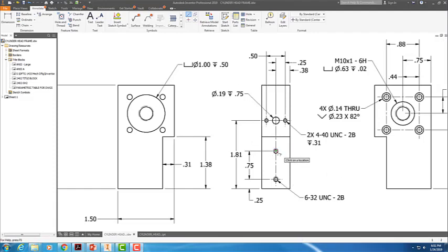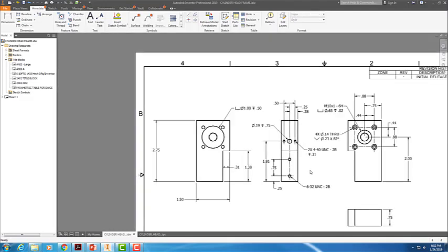The question was, why don't I just put a center mark in here? I could do that. I love to use the automated center marks tool. It makes sure that I don't miss anything. So what I'm going to do is gather every view and do automated center marks all at one time. Alright, so we got those. And I only do it on this type of retrieving because I don't have an input sheet, and usually I put in all my automated center lines first.